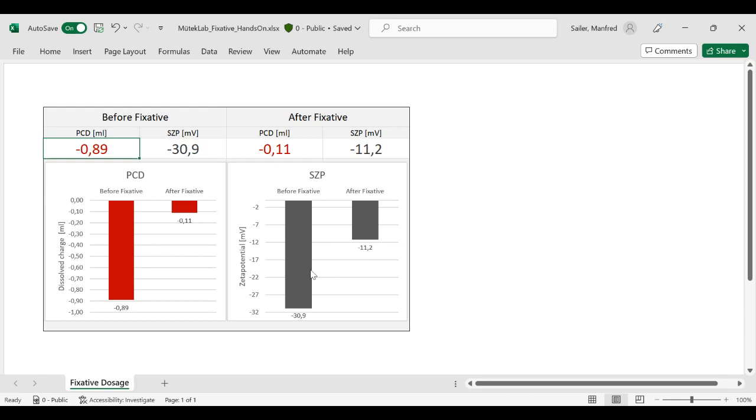And by this, we have subdued the fibers in efficiently reacting with fiber additives. So almost two thirds of the fiber charge, we have just in a matter of seconds demolished by this fixing agent. And this capacity is now missing for the fibers to react with fiber additives. So overdosage of fixative we have as a first learning.